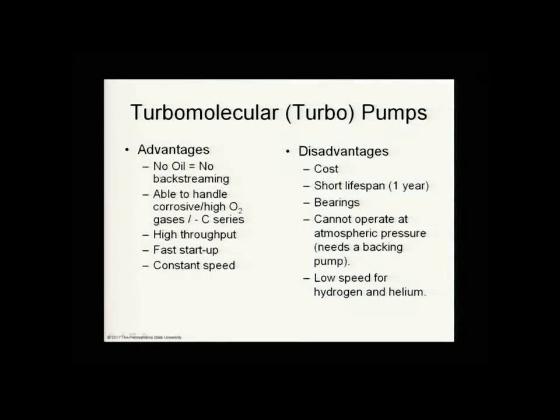Then they also need a backing pump, and they don't pump hydrogen and helium well, and that's easy to understand. This is a momentum transfer pump, and hydrogen and helium don't have much momentum. They don't have much mass, so it's tough to get those to go where you want them to go.